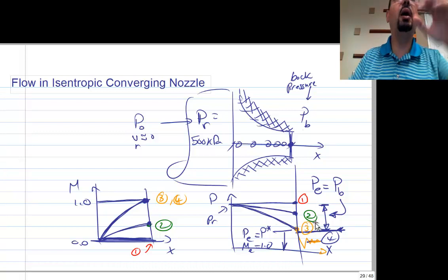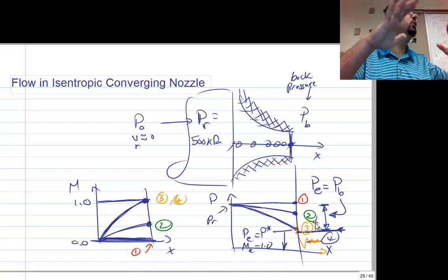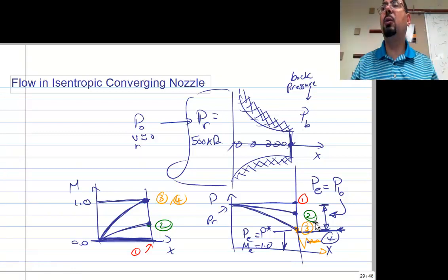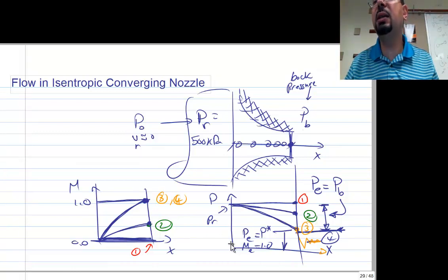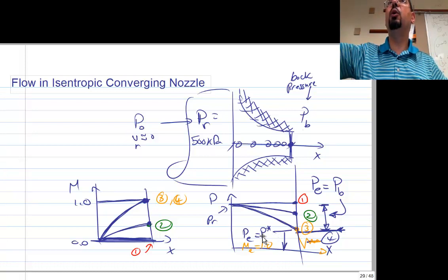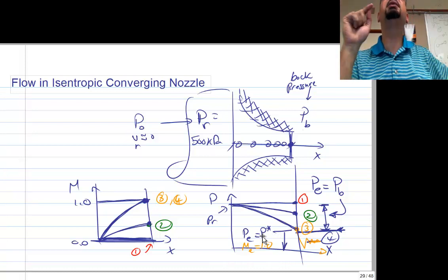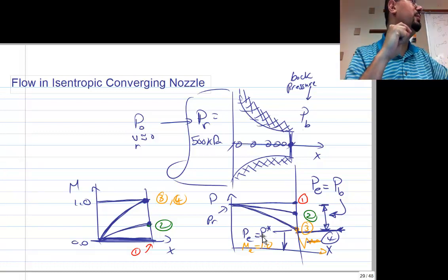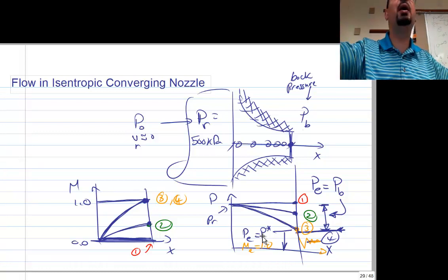Up to this point, this is one regime. Below this point, it's completely different. So at this point, what happened? The Mach number at the exit is 1. And if I ask you what back pressure will do this, at Mach 1, if you open the appendix, that's the pressure you read as P over P naught. This is called P star, because the Mach number is 1.